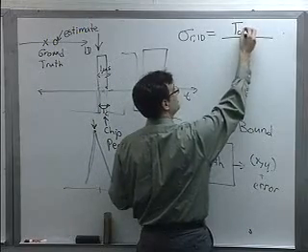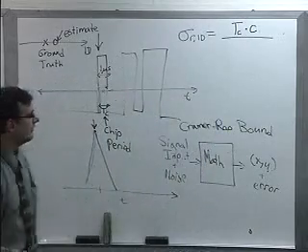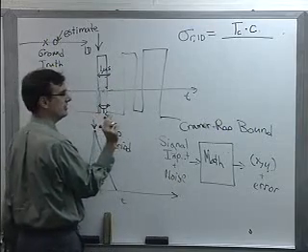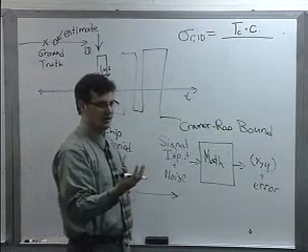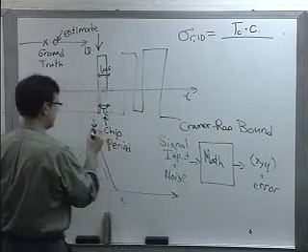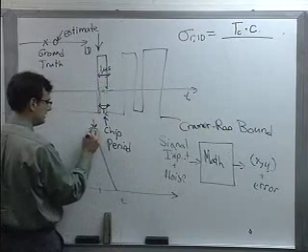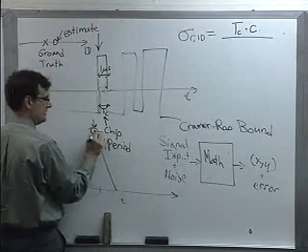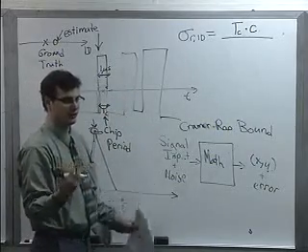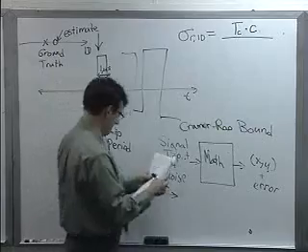So if I take T sub C and multiply by C, the speed of light, or the speed of our radio wave, then this basically gives me that 100 or 1,000 feet of precision as my baseline for just being able to nail a chip. However, if I can measure this peak accurately, it should be a lot lower than that. If I have a nice clean signal, a little bit of noise might distort the peak. So we'd expect some sort of inverse proportionality to the carrier to noise ratio that we receive at our GPS receiver. And that's actually the case.